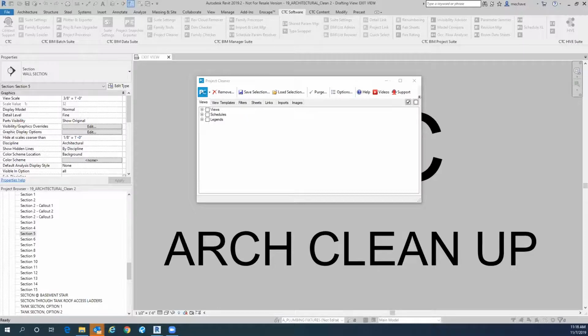Yeah, so how does eTransmit work? It's a really simple process, and that's really what stood out to me, because this obviously goes quite deep. But the eTransmit add-in allows one to select a model as well as all linked models, and combine them into one central location. So if you're a full service firm and they're saved in different folders in your folder structure, it brings them all together, gives them relative links, and puts them all in the same location.